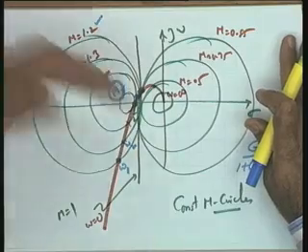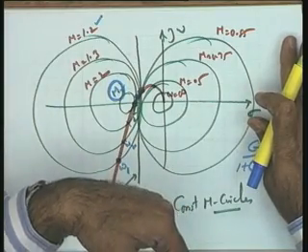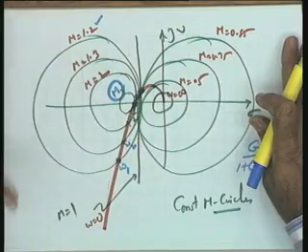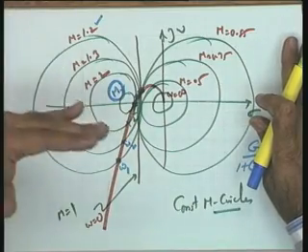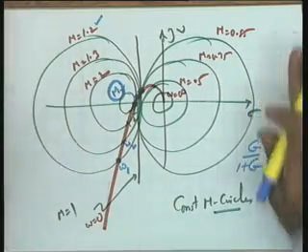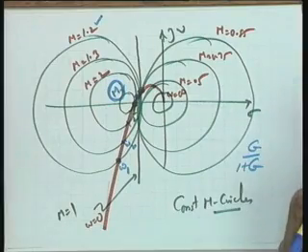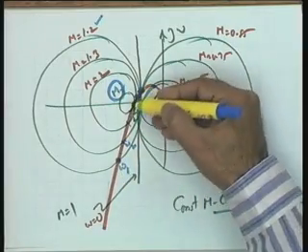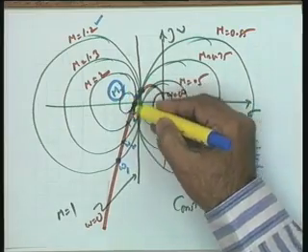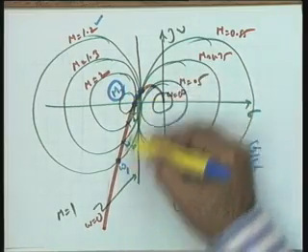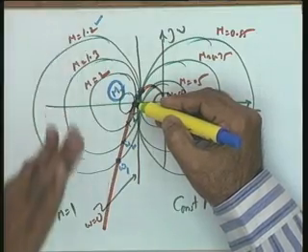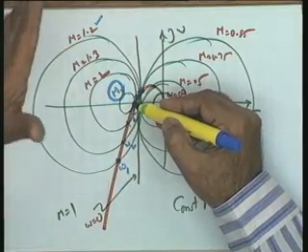This is a route to that particular method, the method called Nichols chart, because that is more practical and that is more easy to implement. However, this will provide the necessary route for that, okay? So, to understand the route very carefully, please see that I conclude my discussion with this, that you just find out this circle to which your Nyquist plot is tangential. That particular circle, the value of M corresponding to that circle is your resonant peak.